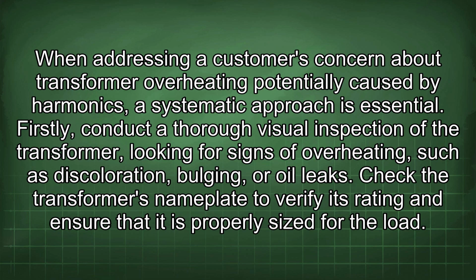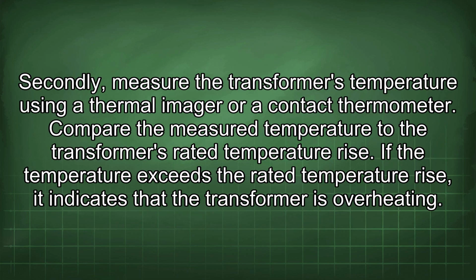Check the transformer's nameplate to verify its rating and ensure that it is properly sized for the load. Secondly, measure the transformer's temperature using a thermal imager or a contact thermometer. Compare the measured temperature to the transformer's rated temperature rise. If the temperature exceeds the rated temperature rise, it indicates that the transformer is overheating.